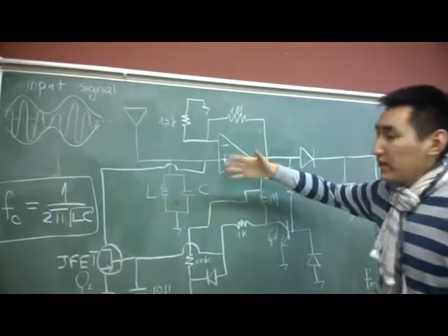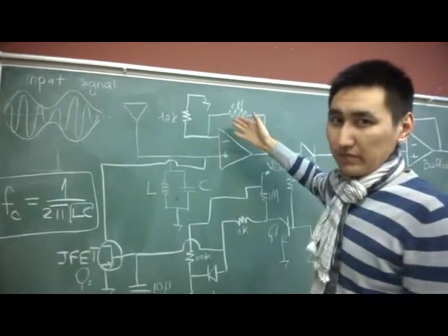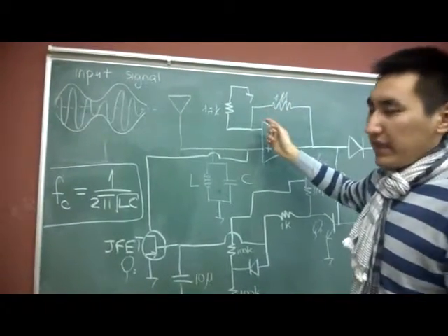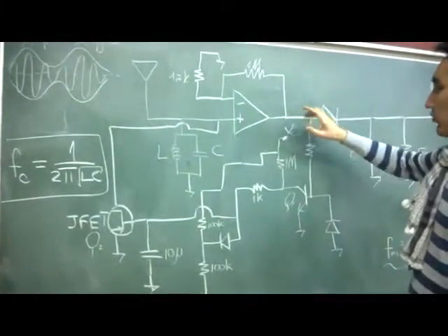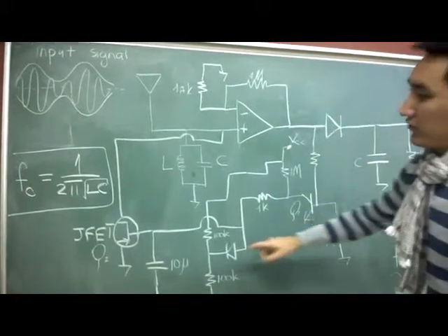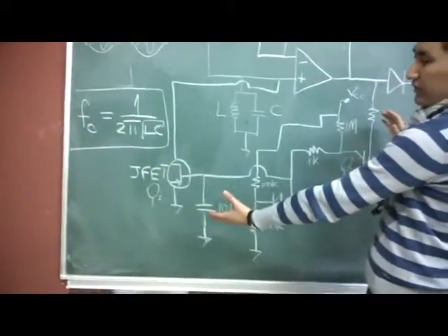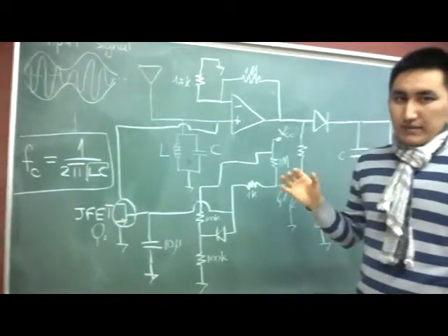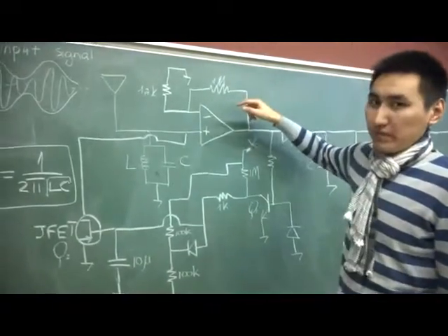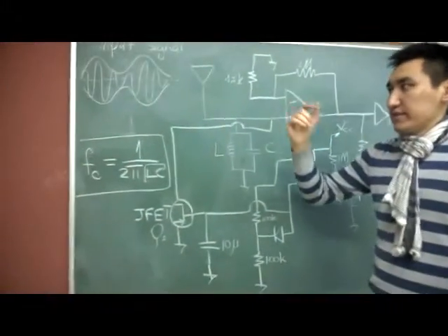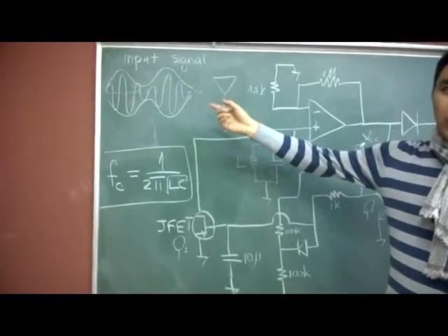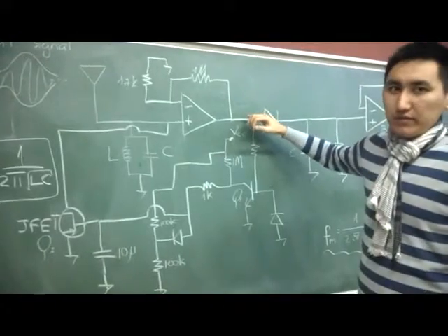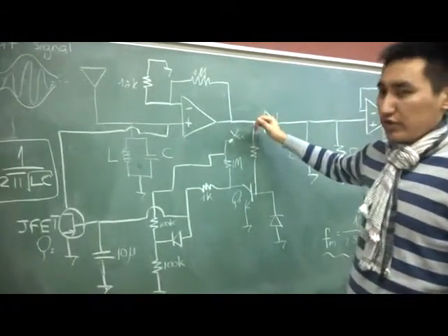to the RF amplifier. RF amplifier is basically a negative feedback amplifier. We play with the resistor values to play with the gain value. After the output of the RF amplifier, we introduce this part, called the automatic gain control unit. The automatic gain control unit is used to stabilize the output value of the RF amplifier. For example, the signal may be attenuated improperly, so we have a decrease in the signal, but our output should be constant. It's asked of us in our project.